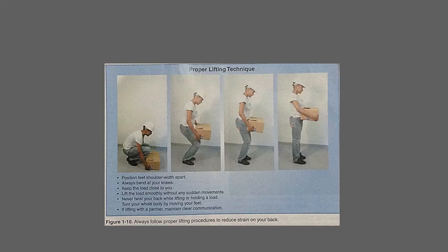Insulated tools. You should always turn the power off before working on electrical equipment. This is the simplest preventive measure you can take to guard against electrical shock. There may be times when you will need to work on equipment with the power on. In these rare instances, you should use insulated tools and the proper PPE. Insulated tools have a non-conductive covering that prevents the transfer of electricity from the tool to the user.